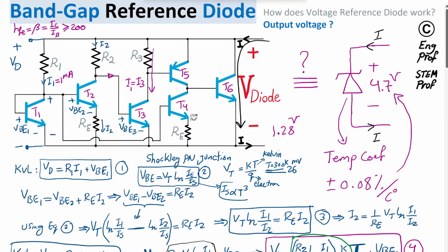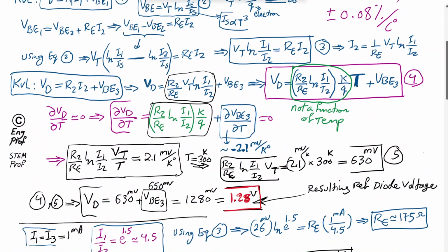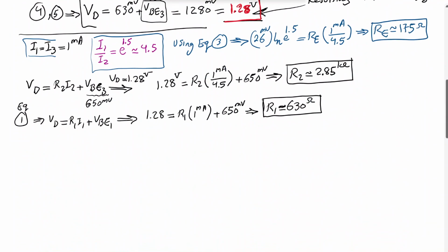Of course, the R3 selection can also be easily done because it's going to be equal to the voltage of emitter base of this PNP transistor. That's the VEB of transistor 5, which is our PNP transistor. So what I can say is R3 I3 is equal to the nominal voltage, VEB of transistor 5.